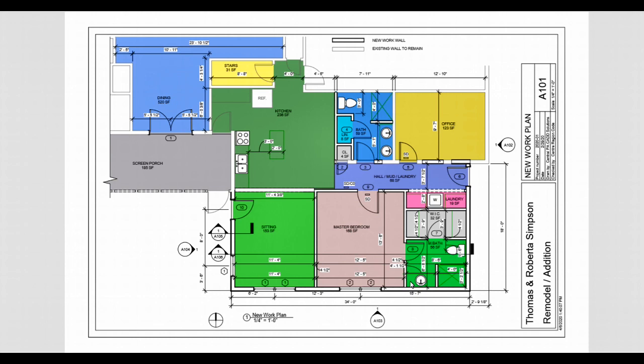I'm basically going through using standard dimensioning, like a 4-foot shower or a 61-inch vanity top for a double vanity, and a minimum of 3 feet for my toilet compartment space. And I could actually take that down to 30 inches total, but that's pretty tight. I like to stay within 32 to 36 inches for this toilet compartment.